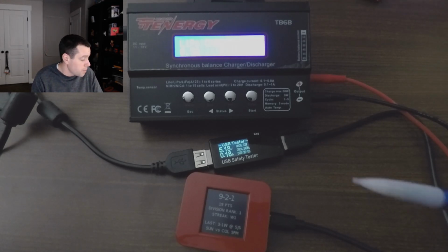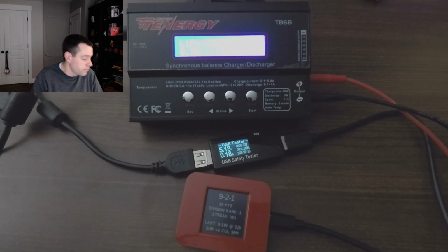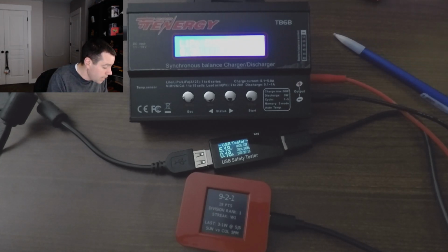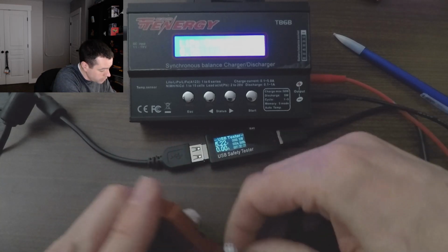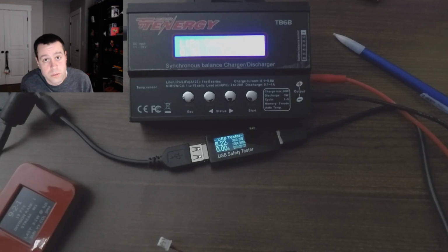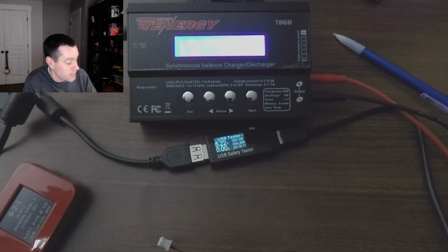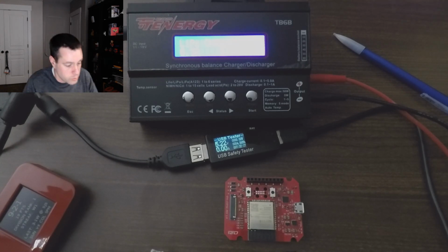I'm getting 180 milliamps. Now, if I were to watch this for hours or whatever, it would eventually start tapering down. It'll get to that 9 milliamps at termination, and then it'll cut right off. So great. That is working exactly as I would expect. Perfect. We're going to disconnect. So, shocker, the original hardware that I've tested thoroughly and have shipped to customers is working as I would expect. Now, this guy is where we've been running into some problems. And so what I'm going to do is switch screens again.